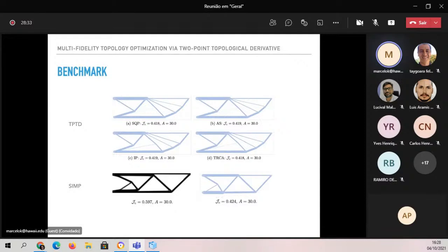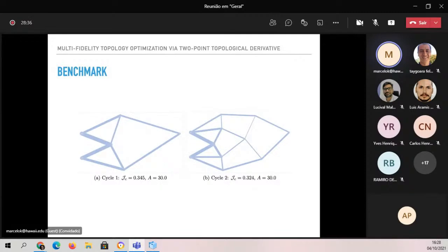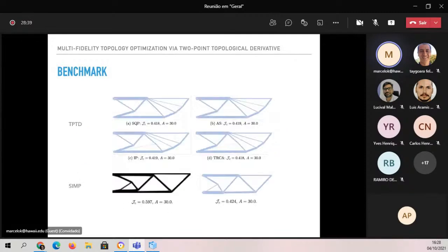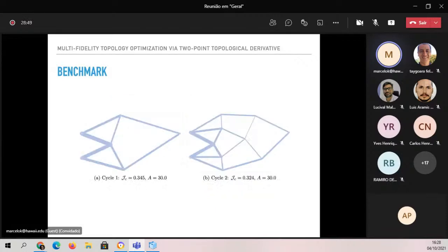Okay, and we can also do some things. This is a classical benchmark for these topology optimization methods, but we can do the things that SIMP can do, and some other things that SIMP will have a hard time doing, which is, for example, allowing the domain to be the full domain, the infinite domain. Because in many problems, you actually don't have a restriction on where to place material. You could place it in any place, right? If you have a crane, for example, you don't have to put this domain here as in SIMP.